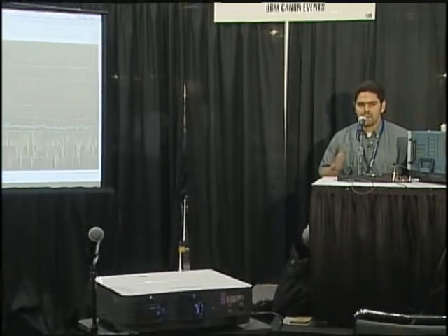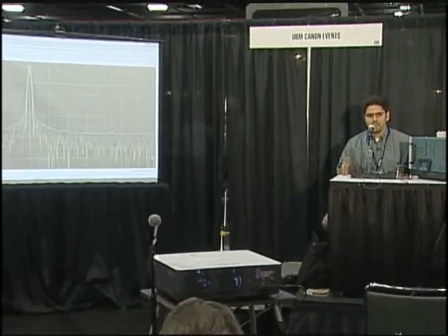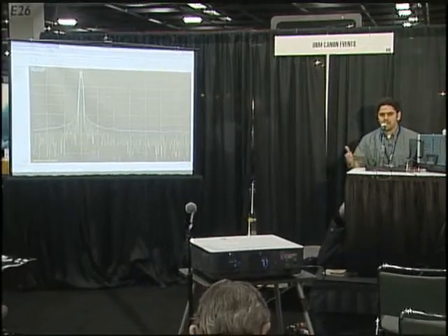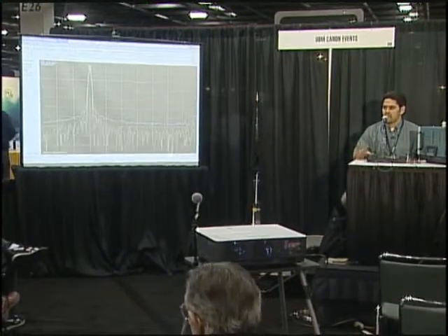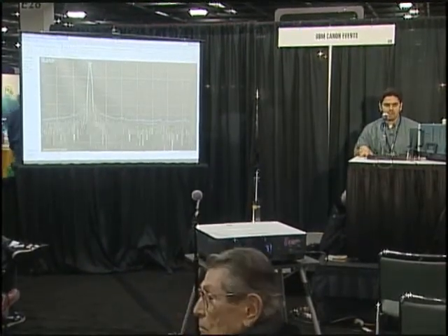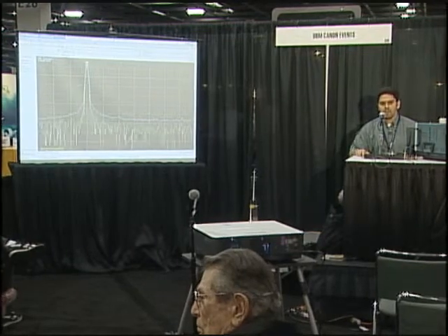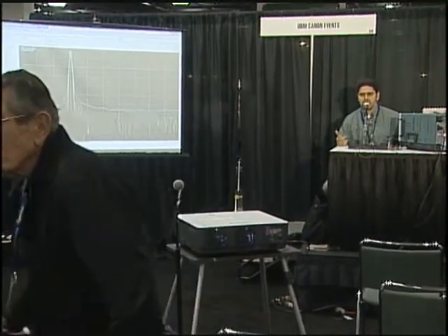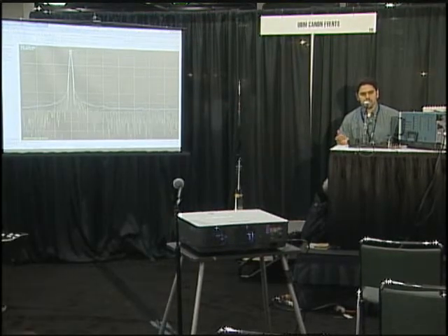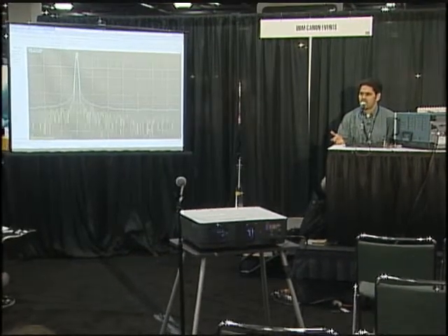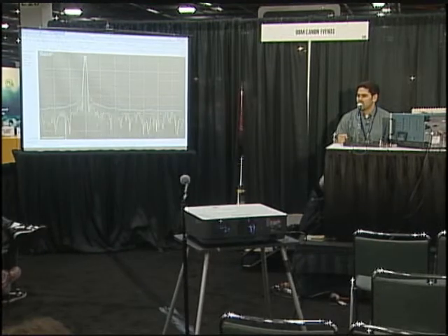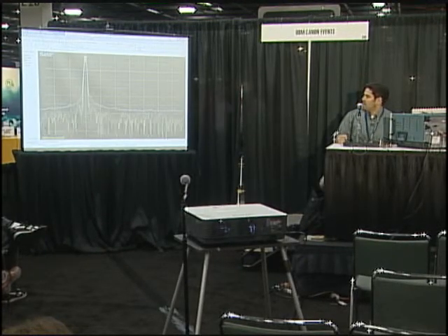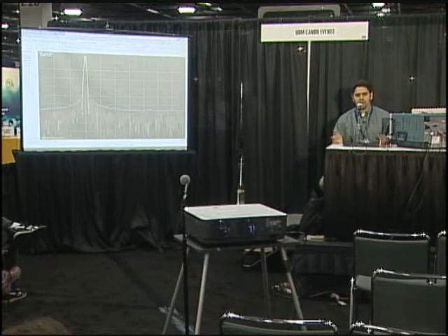So this is a digitizing machine that has a down conversion stage. Then the signal is digitized at that point, and then fully down converted to baseband. At that point, you end up with the IQ of the signal in memory, right? And so we do a lot of math on the signal to show you the spectrum, to do digital demodulation, to show you the time domain of the signal, etc. And that's a regular or traditional